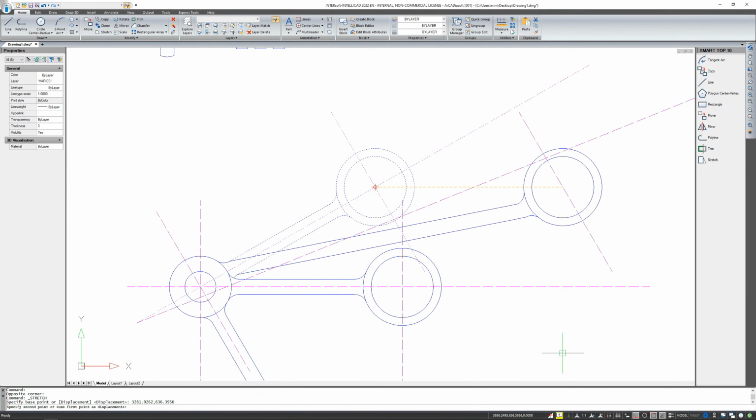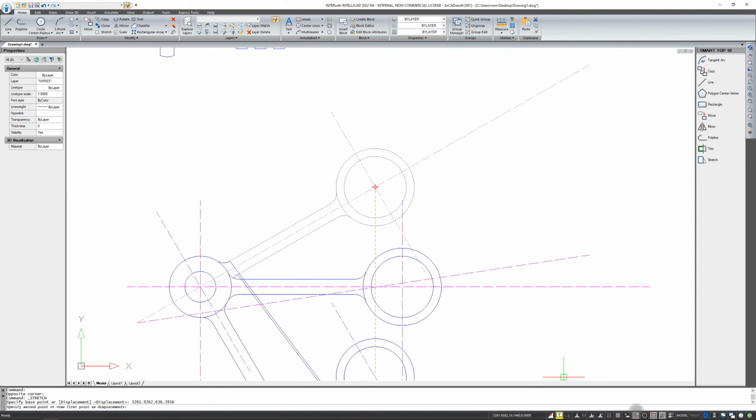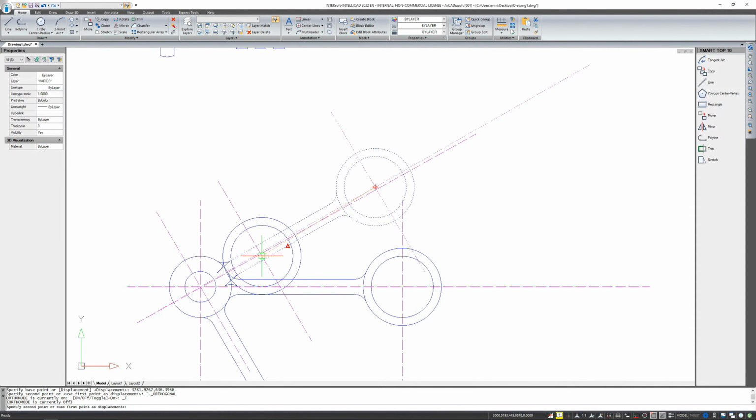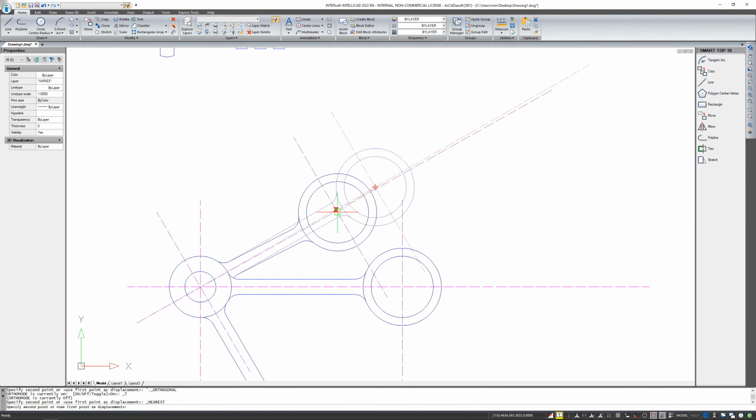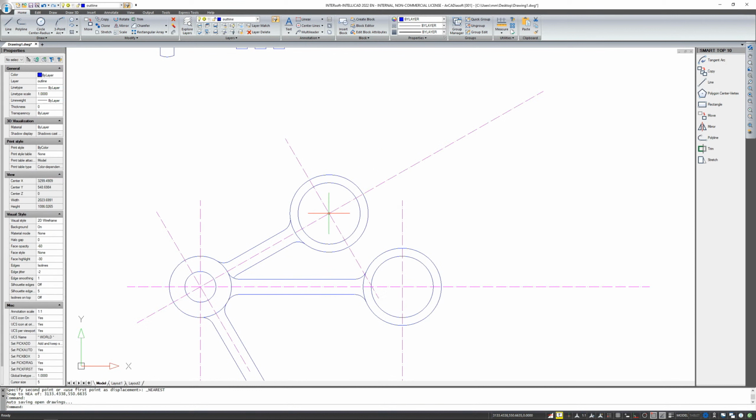But I can of course also shorten or lengthen. I turn off ortho so that it does not interfere. Shortening and lengthening is mainly used for this, but of course, as you can see, I can also move it a bit differently. What I have marked, that is, these points are attached to the element that is being modified. In turn, the beginnings of the lines that I have marked are permanent elements. These elements will not move. So now I can either type or pick the point where this element will be shortened.